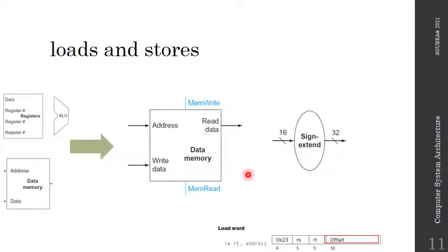Let me think about it for a second. Let's focus on the load. So here, as an example, load will specify the base and the destination address. Fair enough. These are those registers. However, I need to specify the offset, and apparently I'm using 16 bits as an offset here. So hold on. I'm creating a data path that is generic enough to include each and every type of instruction that I talked about earlier, right? Including the loads and stores.